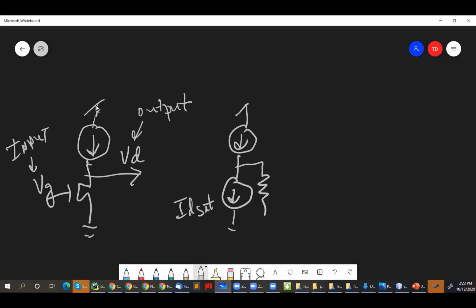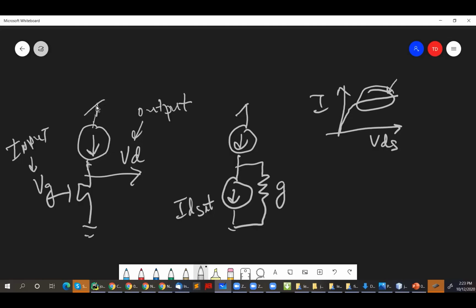What you need to put in now is this extra resistor, because if you remember the curves that you get, if you plot I versus VDS for a particular VG, you get something that looks like this, right? If you operate this transistor in saturation, then you have to include this effect of a slope to your I versus VDS curve. This conductance is now reflected as a resistor. So you say that G here, the conductance of this resistor, is GD set over the voltage, okay?